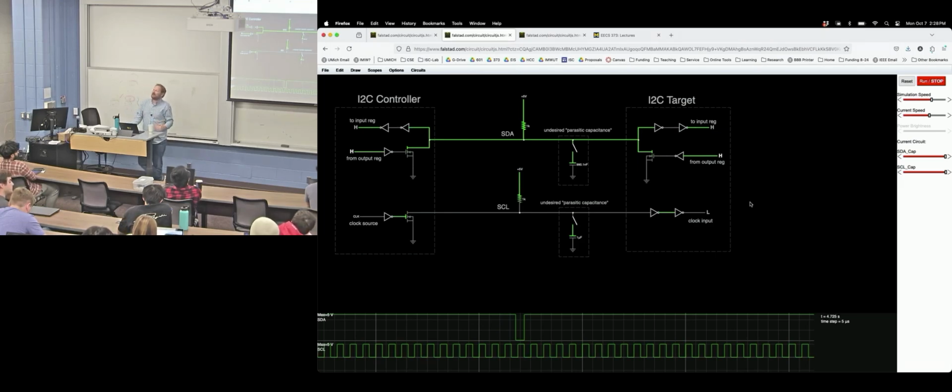Yeah. So is there state? Yes. So your resistor could be so large that it can't pull enough current fast enough for your given scenario. That's true. Typically, I worry about driving too much current through a GPIO pin and burning it out, like through a transistor or something. I worry about those things when I think about the error conditions where a device fails.